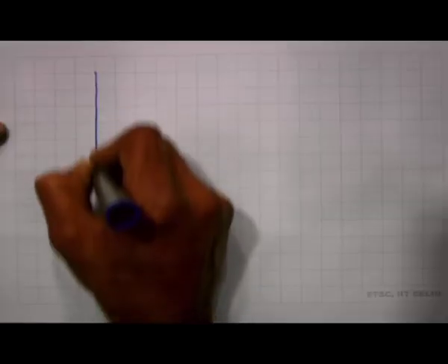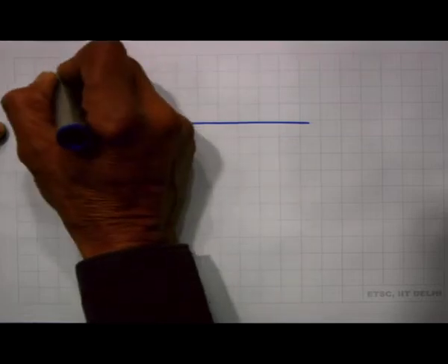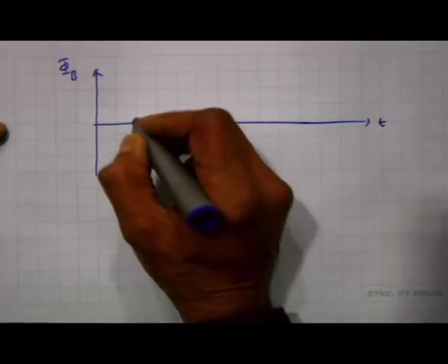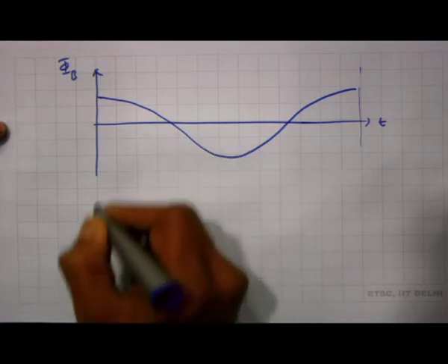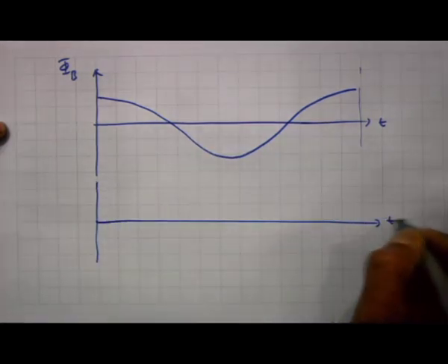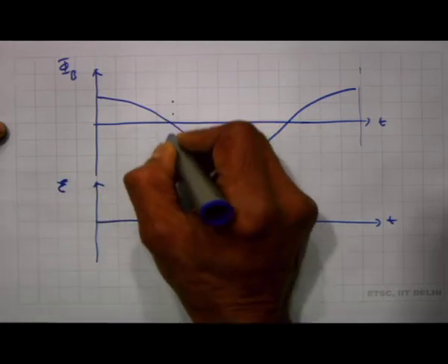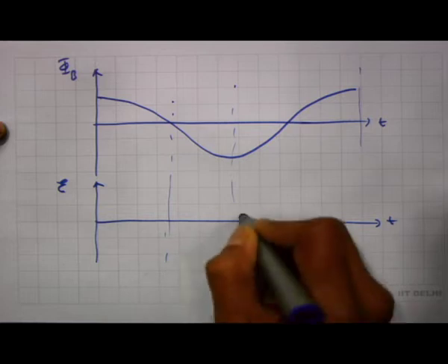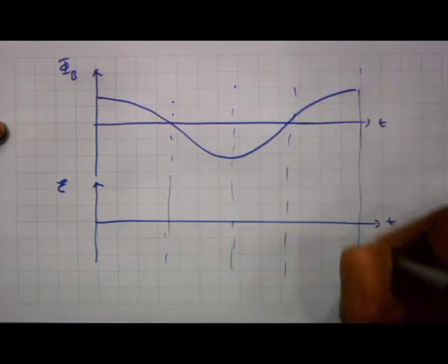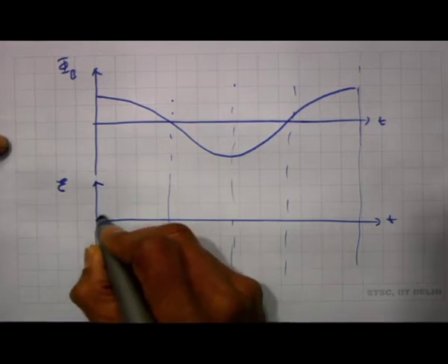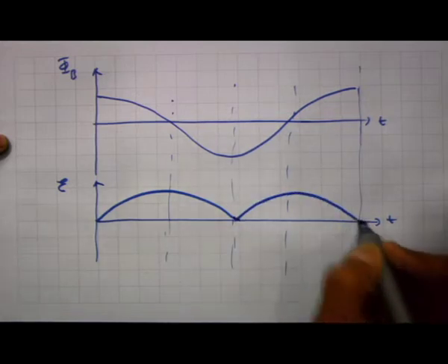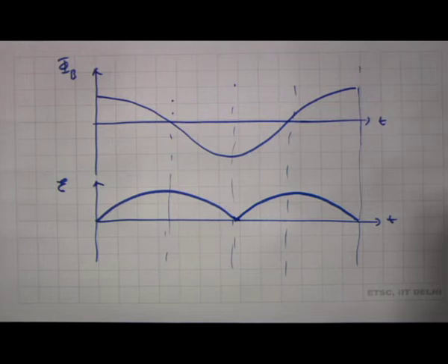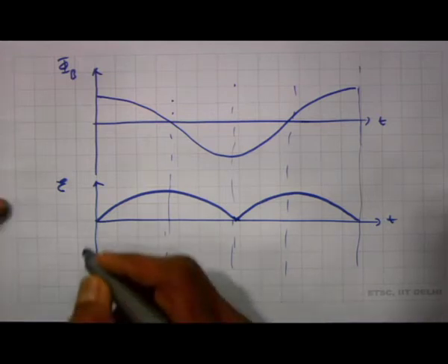If I were to draw phi b as a function of time, suppose it is like this, just like before, this is one cycle. Let me draw the induced EMF here. So, this is 1/4 of a cycle, half a cycle, another quarter of a cycle, full cycle. Just like before, the induced EMF will first do this, and in the second part, instead of going down, it again does this, because the two terminals have interchanged themselves for the outside circuit. The EMF is always positive. And so here the coils will be looking something like this.